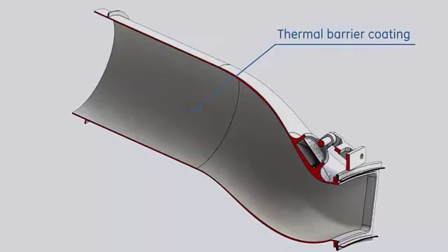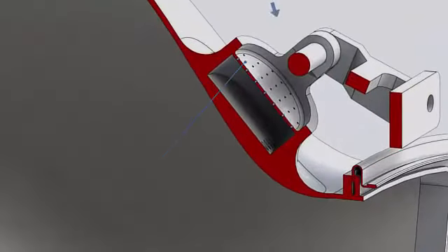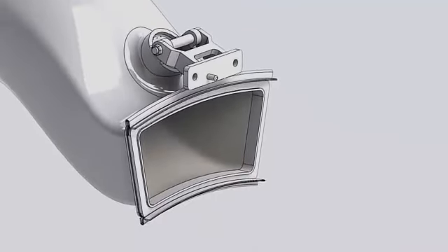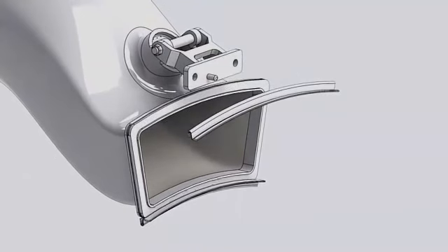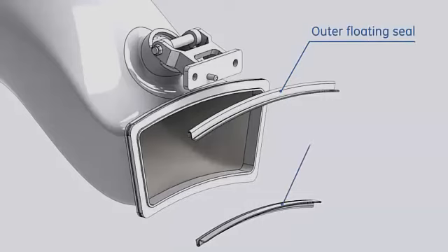with thermal barrier coating. Cooling air is introduced by allowing compressor discharge air through the vent plate to the cooling holes machined on the transition piece aft end. The transition pieces are sealed to both outer and inner side walls of the first stage nozzle by the outer and inner seals.